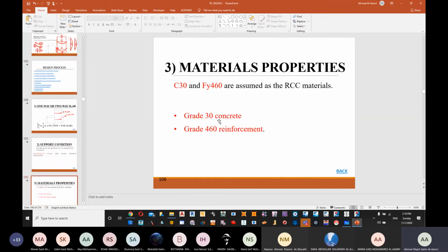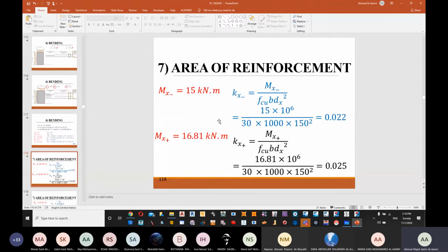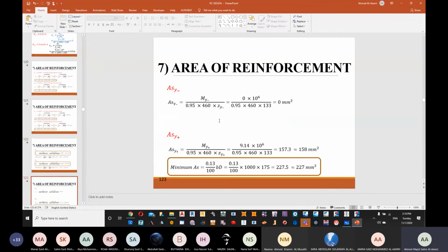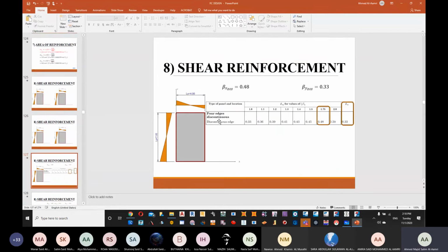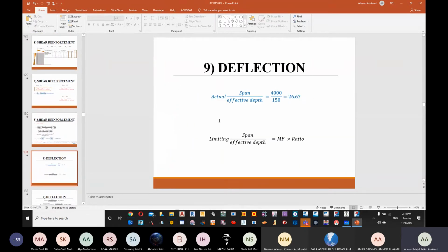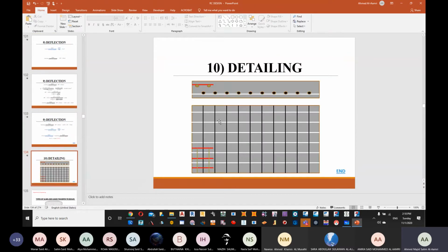Okay. Now, after talking about the slabs, I have given you already one full problem, and then I have illustrated a different case. We have already explained shear, deflection, and everything. Things are going to be the same. The only thing, the cases, the values are going to change, the detailing as well. Now you can see here, we supplied only the top reinforcement. We have only supplied for the position where continuity is there.